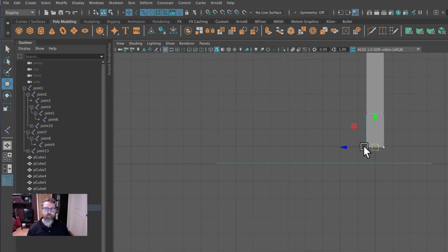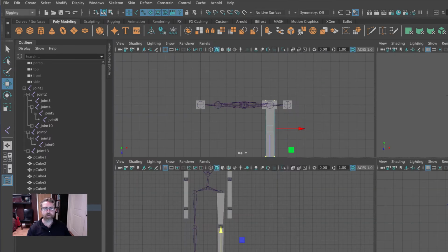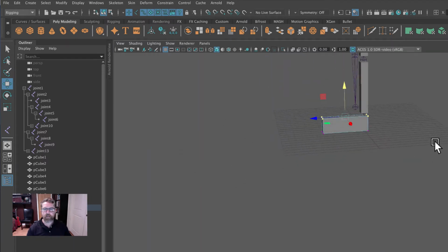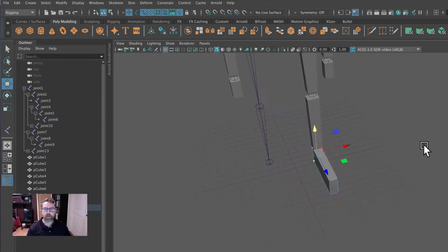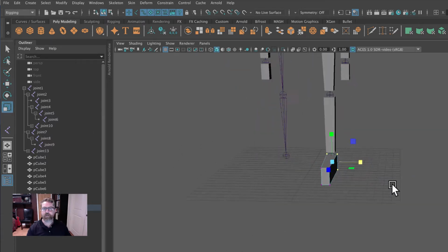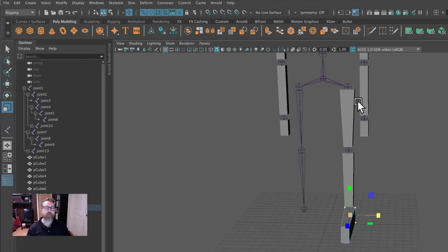Right, I had these two vertices selected. You can click on the arrow there and hit the X key. And then we'll grab these and pull them forward. And we'll grab these and just pull them down. So we just got a block foot, just a stand-in foot. But as I've mentioned, you can create better geometry once you're done animating and simply swap it out. You could delete these pieces and go to File, Import, and reparent them in.